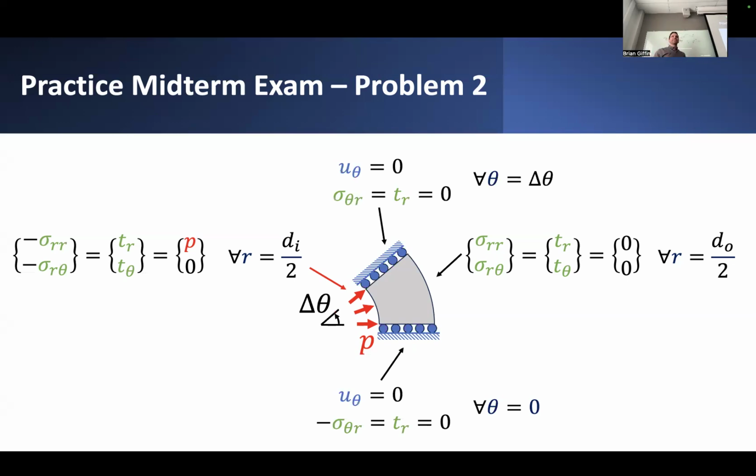So in all, it might look something like this. And if you'd like to visualize it, as I do, you might think of these symmetry planes as being replaceable with roller constraints. So there's no constraint on the actual radial movement, but there is a constraint on tangential movement. You could equally just replace these symmetry planes with a collection of rollers. Rollers that could still sustain some kind of tensile force, so they're magic rollers, but nonetheless, visually, that's how you would rationalize it.